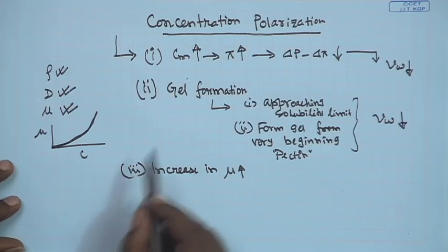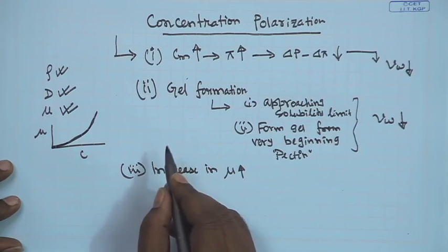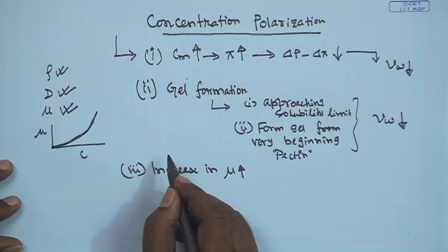In case of osmotic pressure control filtration, the membrane surface concentration is 3 to 4 times the feed. For the gel layer filtration, this can go as high as 50 to 100 times. Even in some cases of osmotic pressure control filtration, for example using dextran, the membrane surface concentration can be as high as 25 to 30 times the feed concentration.